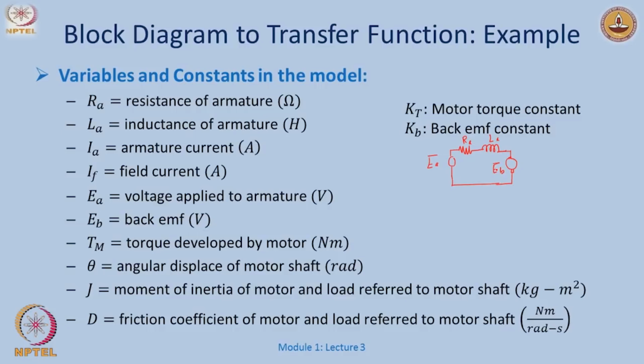So, the first of my equations, if I were to write it down, would be E A equal to, if I call this I A from these notations here, I A R A. I write everything in the Laplacian domain: R A plus S L A plus E B. Or E A minus E B is I A times R A plus S L A. Okay.